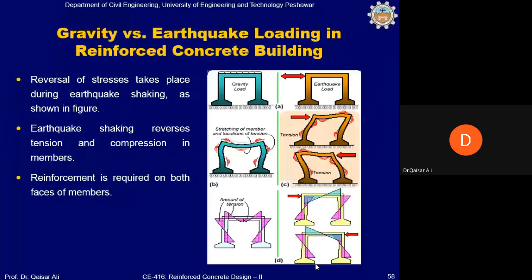Once concrete cracks and deteriorates, the steel will be exposed to air, and steel can then get corroded. And in other situations, steel is placed in piles in bridges, for example, deep down in the earth. In these situations, the steel is highly exposed to corrosion.